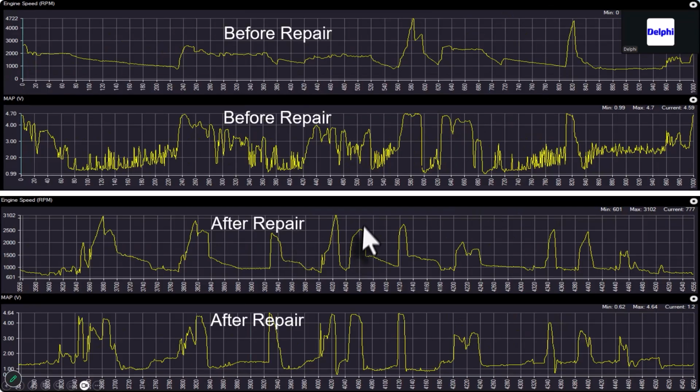So I'm running this by my good buddy. We're thinking, geez, on deceleration, where could I have that kind of manifold pressure change? The car runs great. Lo and behold, what we came up with, we told him from 2,000 miles away to put a PCV valve in this car. And he did, and look at the pattern on the bottom.